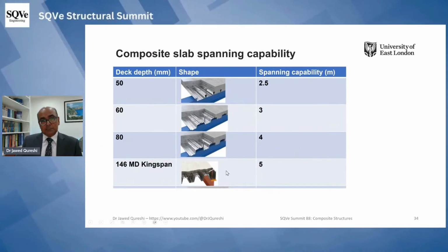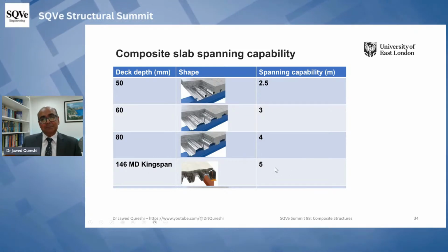And if you work out the strength of shear stud connection using this decking, using the Eurocode formula, you will get wrong results. That will not be realistic. So this is a knowledge gap that needs to be filled.